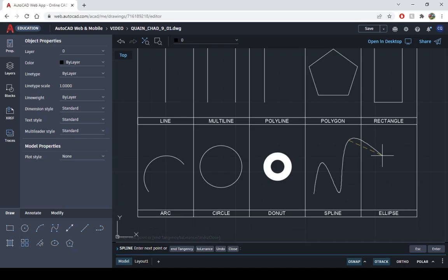Now, normally, if you had straight lines, this would be a heck of a roller coaster to ride on. But with the spline, it's actually pretty usable. Now, normally we would just hit escape to get out of the command. Well, we can't do that. If we do, it's going to kick us out of the command, so we actually have to hit enter instead.